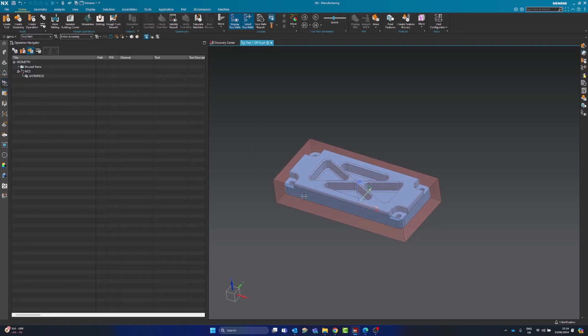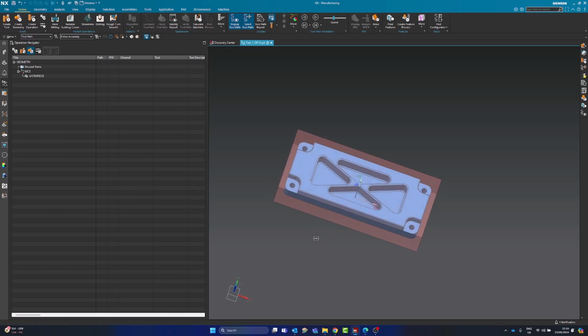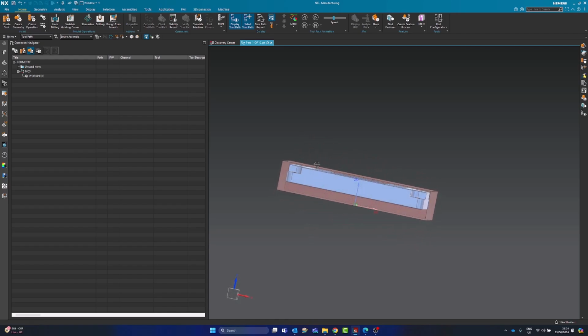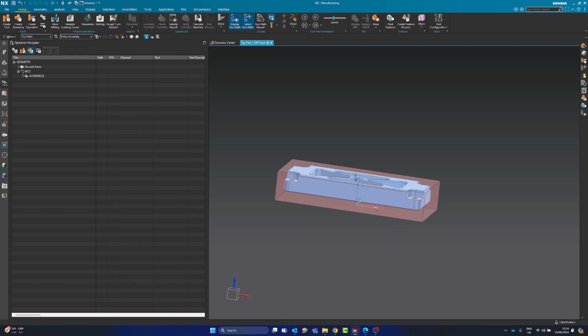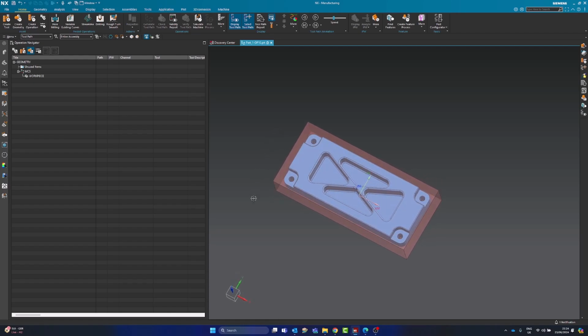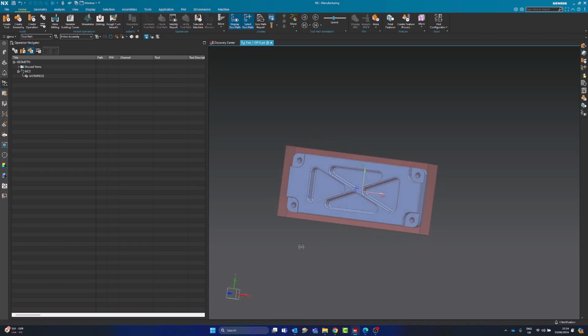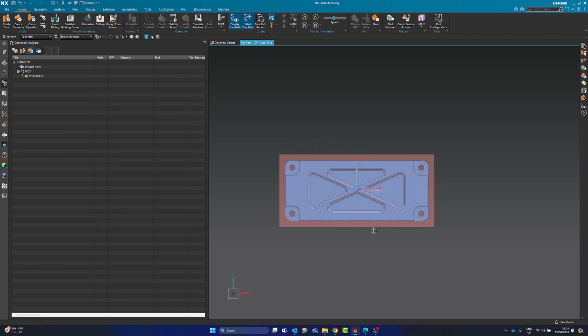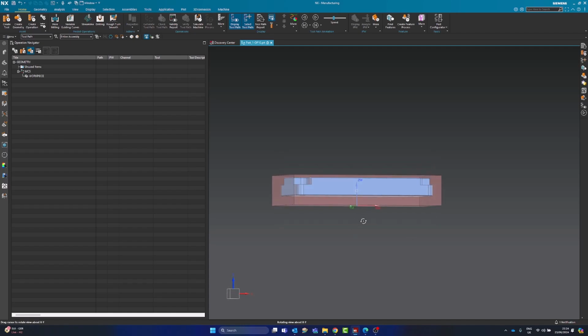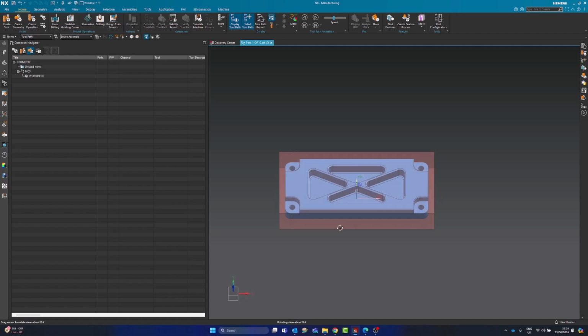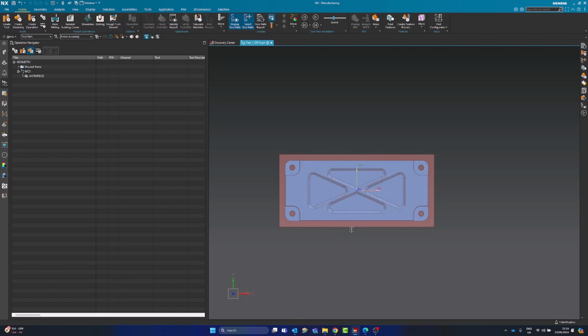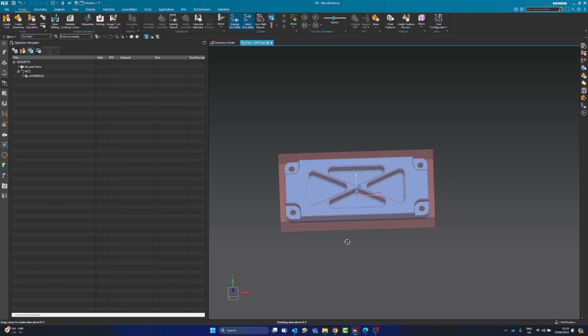Okay, so this is the part where I'm going to start thinking about my first toolpath. We obviously have 10 mil of stock on the ends, and we have just a little 2 mil from the top, so it's not just like a flash off the top. So straight away, I would be thinking of some kind of trochoidal milling toolpath, or a cavity milling toolpath. It depends how you want to take this stock away. But for me, with the depth of this not being that much, I would trochoidal cut the outside of this profile to rough it out, sort of coming in like this and round. And I'll show you the differences between cavity and trochoidal in a moment.